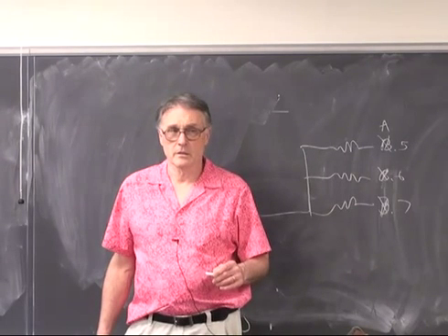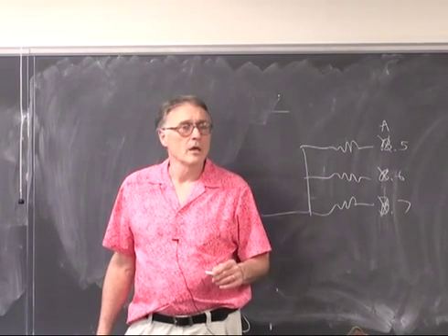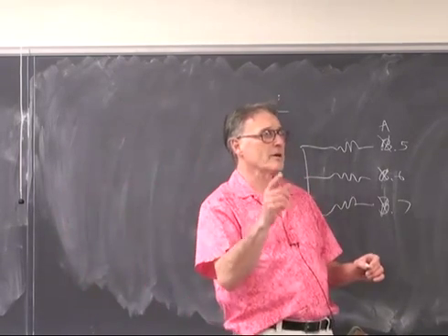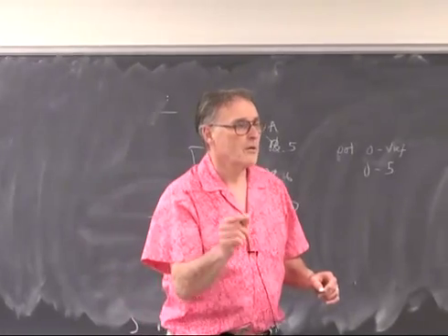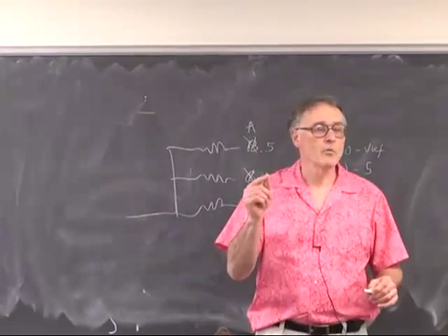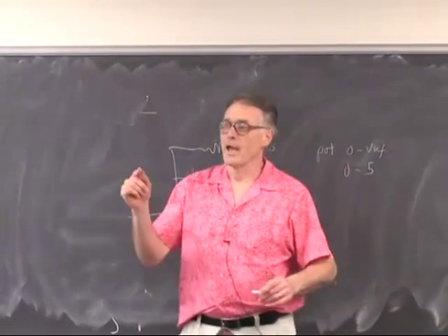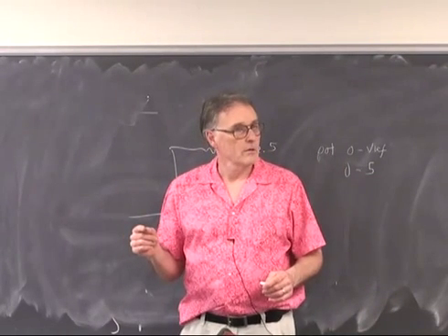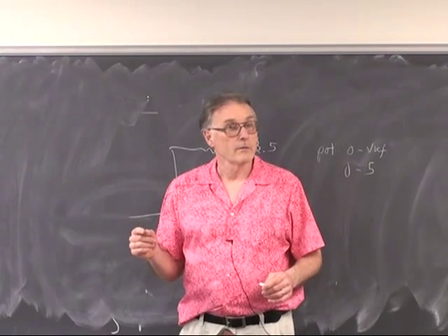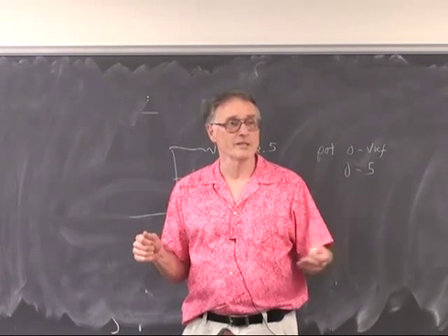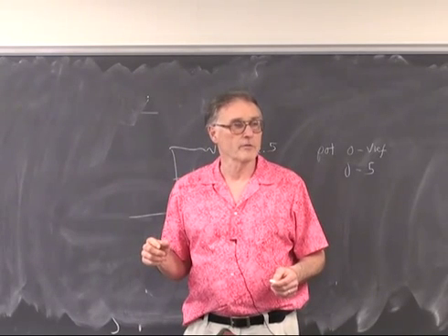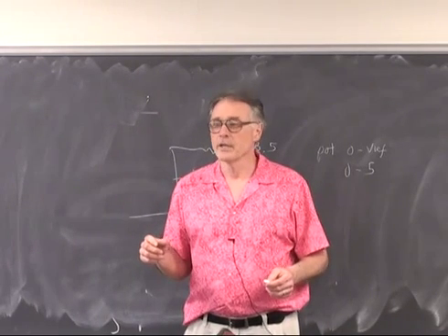The reason to go to 100 hertz is: at what frequency of square wave input will timer 1 overflow at full clock rate? Very good. About 4 milliseconds, very close, just slightly over. So it'll overflow at 244 hertz.